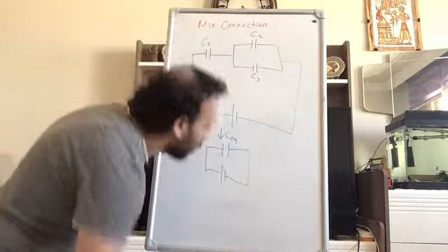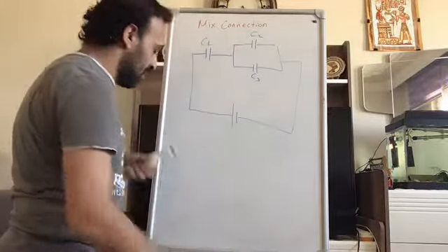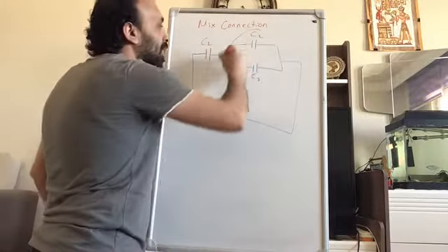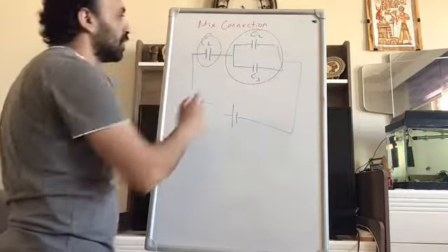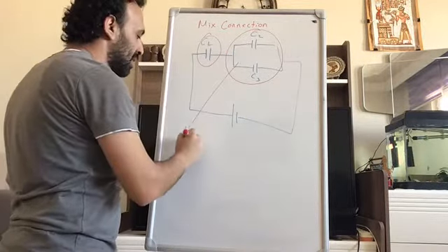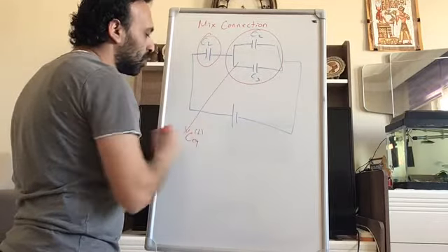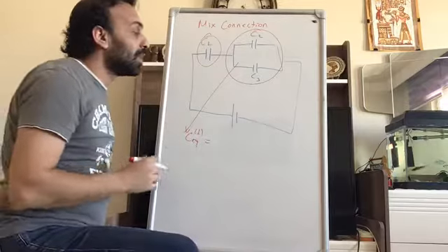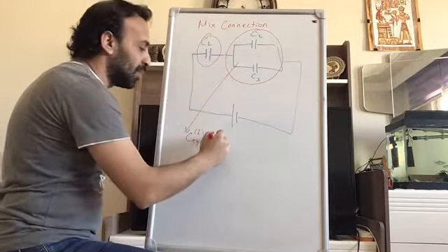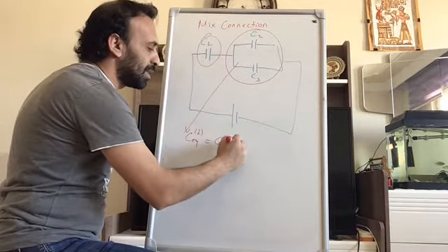How can we calculate? First, we need to calculate these parallel ones, and then move to this one. So if I call C equivalent part 1 of here, actually from the previous discussion we know it will be equal to C2 plus C3.